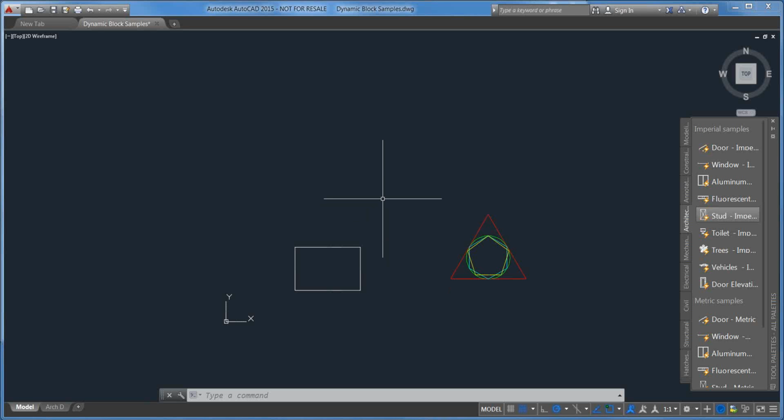The parameter defines what gets modified, I guess. So like the linear parameter says we're going to adjust a length type of property, and then the adjustment is the action. When we adjust that length, are we saying stretch the object or array the object or something like that? So yeah, you have to assign the action after you assign the parameter to be modified.